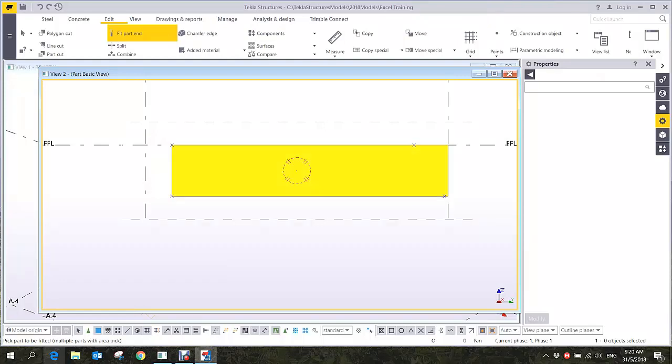And that's it. So look, the fitting means it will cut the smallest part of the element. So let's say you have a 10-meter beam, and then you cut at 4.9. So it will cut the 4.9. The 5.1 will still remain. So it will always cut the smaller part. Okay? If I want to keep the smaller part, how? That's another story. Another command. So that's why I want to show you that one first.